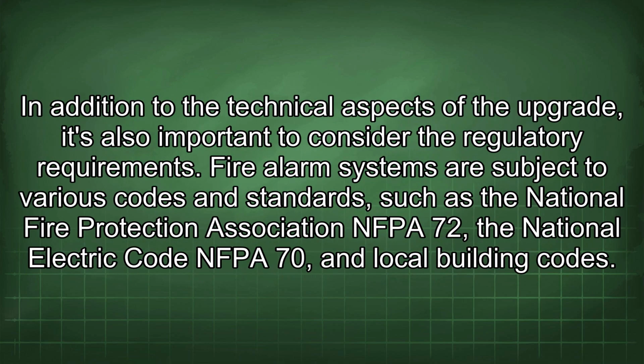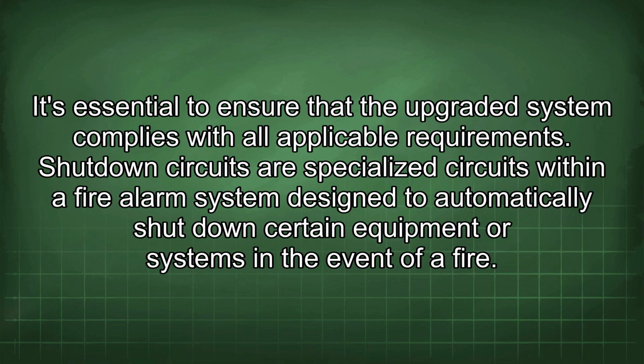In addition to the technical aspects of the upgrade, it's also important to consider the regulatory requirements. Fire alarm systems are subject to various codes and standards, such as the National Fire Protection Association NFPA 72, the National Electric Code NFPA 70, and local building codes. It's essential to ensure that the upgraded system complies with all applicable requirements.